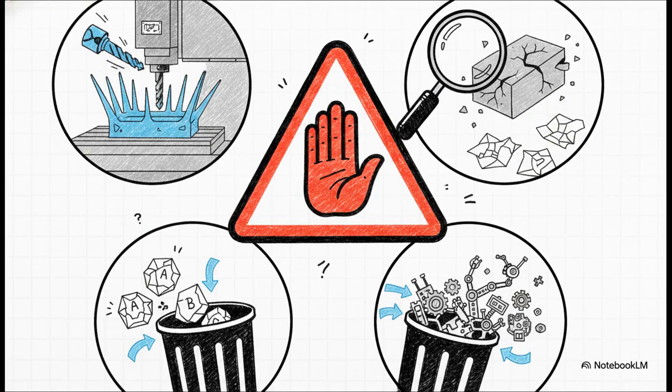But beware, with shiny new tools come new pitfalls. You absolutely must avoid these common mistakes. Never accept an AI design without running your own rigorous analysis. Don't ignore real-world manufacturing limitations. Just because the AI can draw a crazy shape doesn't mean a CNC machine can actually cut it efficiently. Always verify your material selection. Never skip physical prototyping. And be super skeptical if your AI is training on incomplete or inconsistent data. Garbage in, garbage out absolutely still applies in the age of AI.